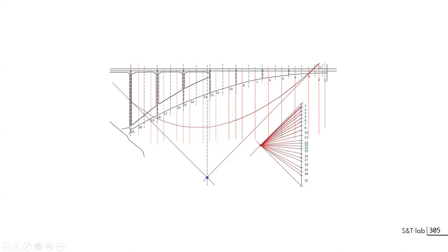You know that starting from the head, it's just 45 degrees and you get this intersection point. You know the equilibrium of three forces. You have here the resultant and here the two side rays, but you can also try to find the reaction forces at the middle and at the side.